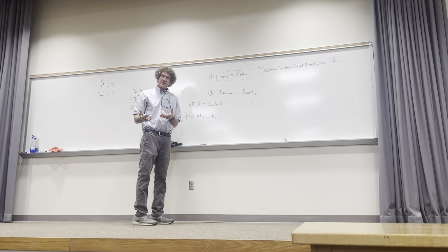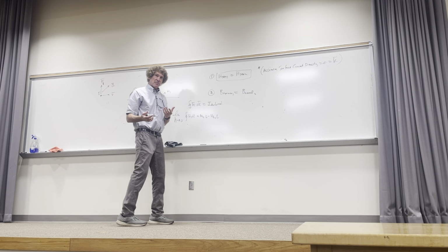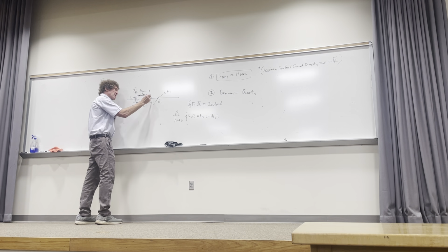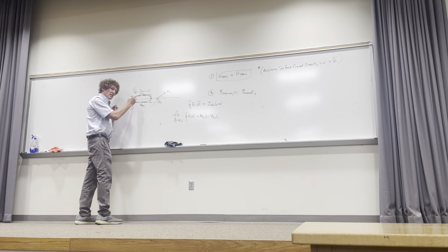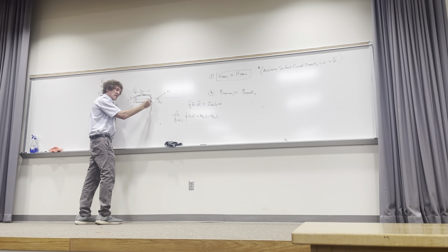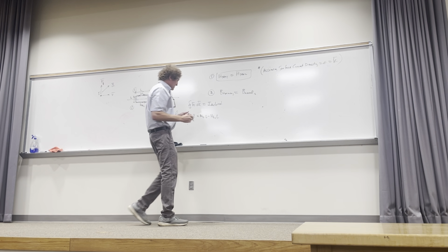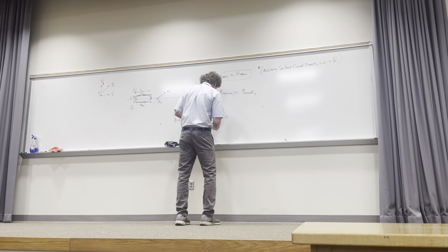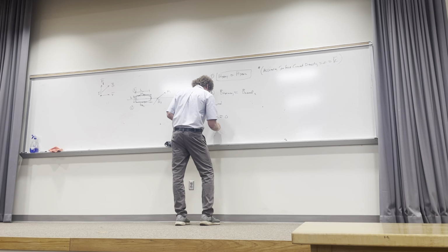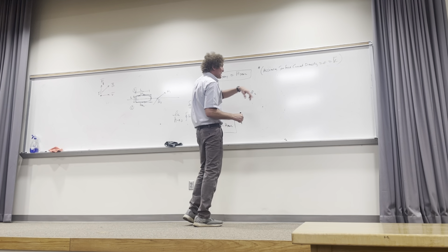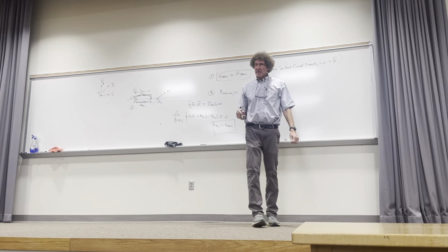You don't have to make this thing into a very hard mathematical problem. But realize when you're doing a path integration, if these two were the same, I would get 0 around a path integral. If I start here and go around, the same amount I gain here, I'm going to lose here, if that makes sense to you. And what this really means, if that's 0, it means the tangent field, H tan in region 1 is H tan in region 2. And that's true always if the surface current density is 0.